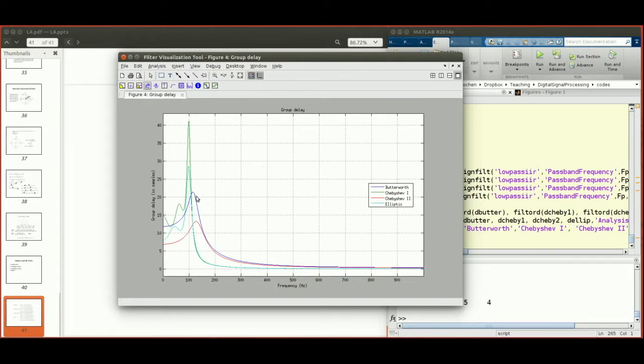So the reason that you are seeing this kind of large amplitudes at the boundary of the passband is just because the change in the phase across the corner of the passband is relatively large. So the derivative is a reflection of that big change. Right. So that's why you see the peak of the phase derivatives, the group delay, maximized at the corner of the passband.